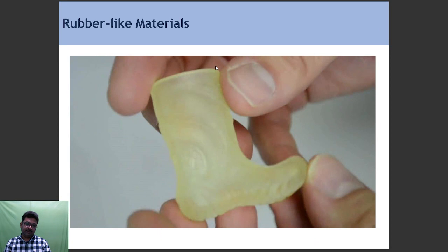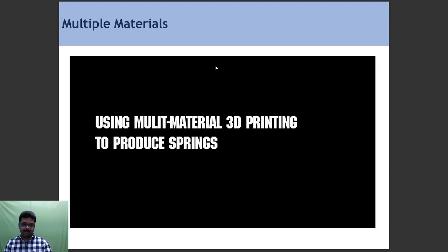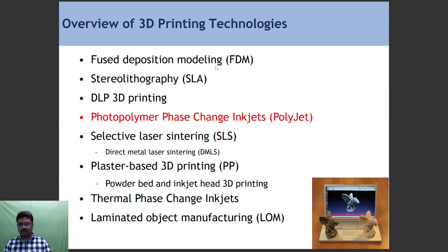products. Okay, these photopolymers are rubbery materials, so we can get rubber-like structures using this technology. In other 3D printing technologies, it is hard to bring in this flexible rubber-like material, but this technology offers the support for us to prepare a rubbery material as well as a product. Multiple materials are also used in this 3D printing technology, where the photopolymer has multiple slots, and using these slots we can add more colors, where the laser light pulls the color into the final product.